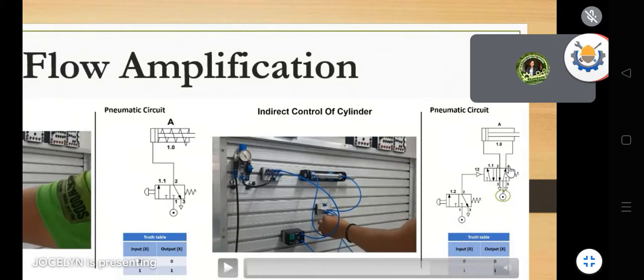You can see it here, guys. This is port 4 of this pneumatic valve, and it should be connected to this port here for the retraction, going back to the normal position. And this port 2 is connected to extraction, meaning the rod goes out. Make sure that not only this 5-way valve but also this 3-way valve is connected to your pressure air, from your air compressor.